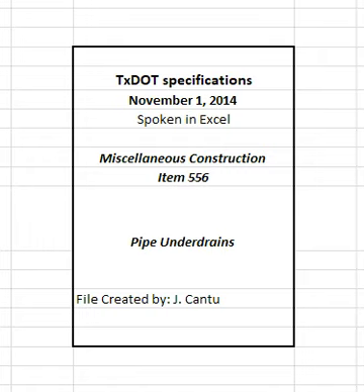2.2 Filter material. Furnish hard, durable, and clean sand, gravel, crushed stone, or crushed shell meeting the gradation by % weight specified in Table 2 unless otherwise shown on the plans. Filter material must be free of clay balls or other organic or deleterious matter as determined by Tex 413A. Do not furnish crushed limestone unless shown on the plans. Use only one type of filter material for any underdrain system on a project.